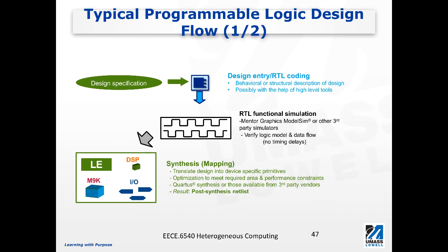And then the developer can use functional simulation tools such as ModelSim to verify the design. But in this stage, only the function is verified. There's no actual delay simulated in this stage.